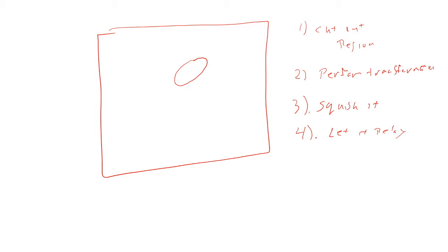And it turns out that this actually has a remarkable solution. I'm not going to go through the solution itself, but the form of it is interesting. So if we do this and we assume everything's elastic, what does the stress look like in this inclusion? Does anyone have any sense? It could be tensile or compressive depending on what the volume change was.